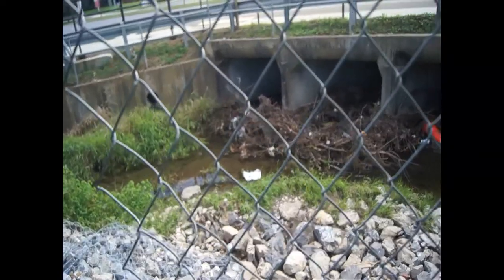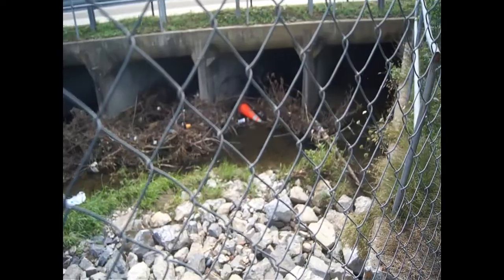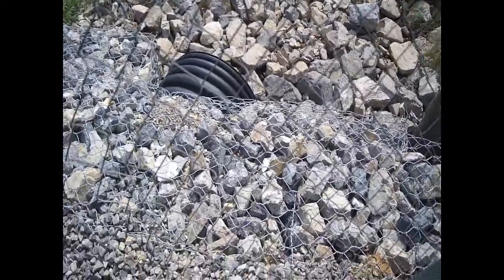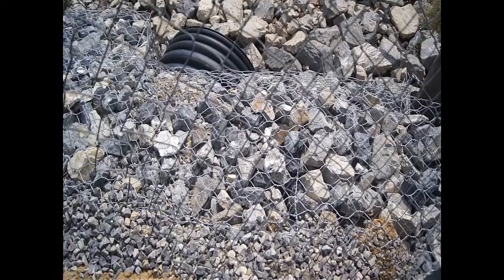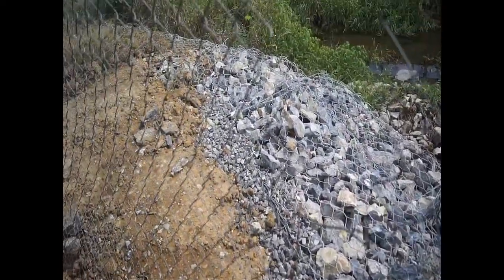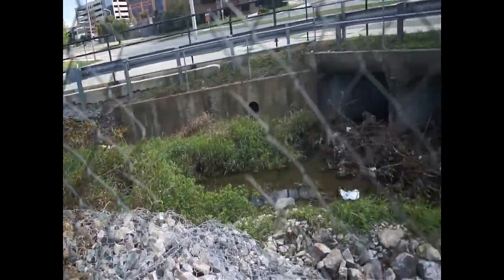Here we're at the bottom of the second sediment trap at the outfall protection. This is the point where all of the water which has traveled from the first sediment trap down through the diversion dikes has traveled into the second sediment trap and is going through this outfall structure to be released back into the stream and protect against too much erosion occurring at this point.